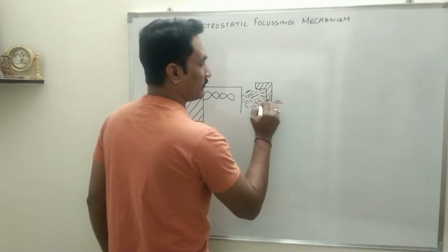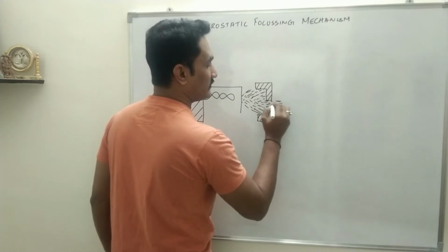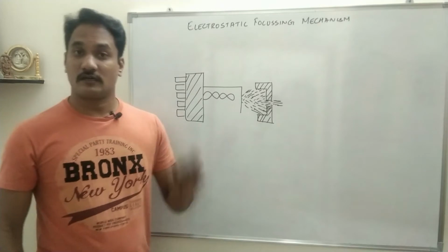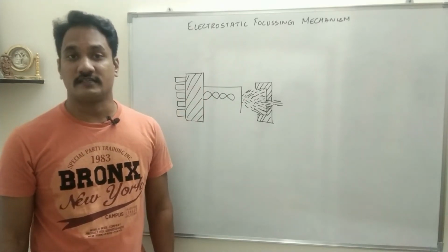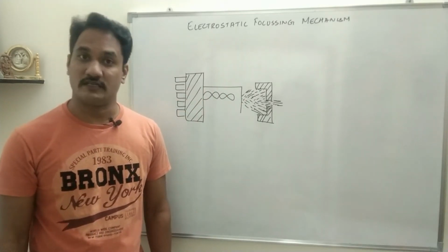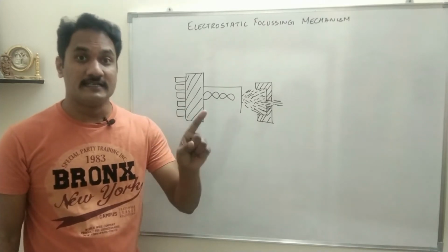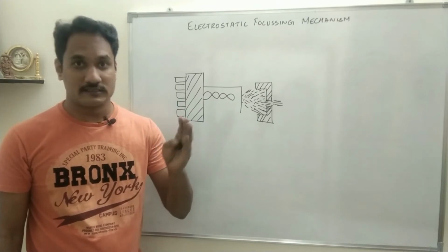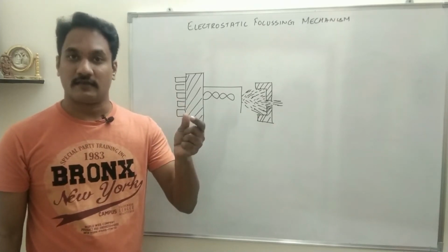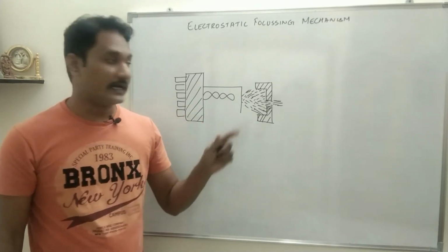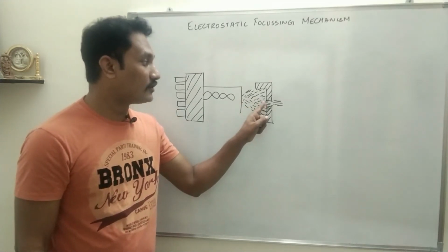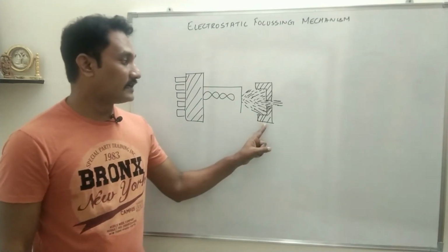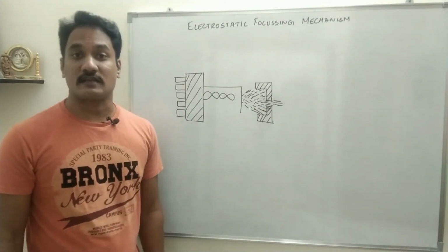So basically what happens is, in the block diagram of CRT, we clearly specified that the control grid is connected to an external negative potential, which controls the intensity of the image on the screen. In easy language, it controls the brightness and contrast, right? How does it control? By controlling the amount of electrons moving out of the control grid.